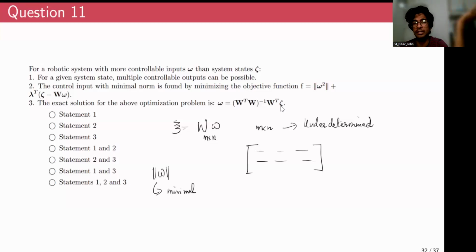As you know, kinetic energy is proportional to the velocity square. So by choosing the minimal norm solution, in effect, you are choosing a solution that has the least amount of energy, so that the norm of all the actuators of a mobile robot would be minimal compared to any other feasible solution.